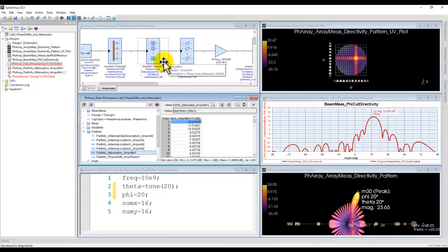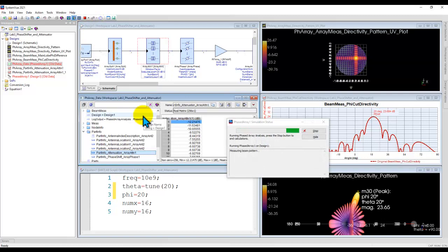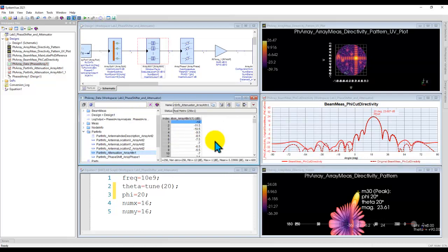But now, after we apply the quantization, when we run the simulation, you will not see these kinds of decimal digits, because now the results will be truncated to the step size which you have just entered. Now you can see in all the channels you are seeing 0.5 dB increment based data. Now if you compare the response, there is no major loss between the ideal attenuator and the one with quantization. You are still able to achieve what you wanted.